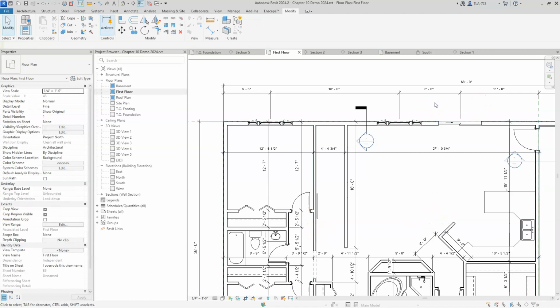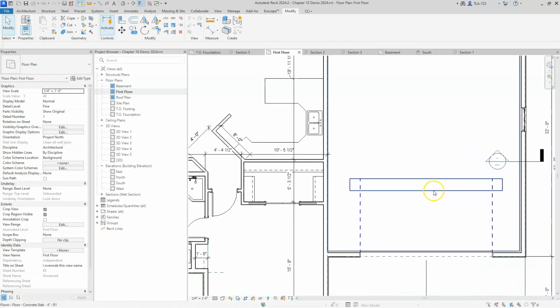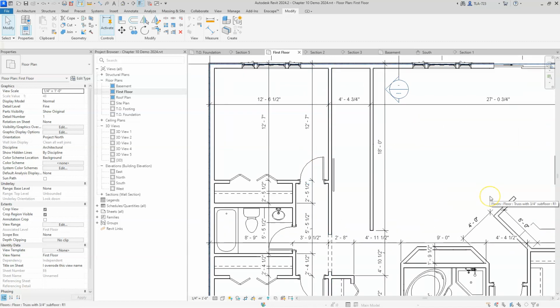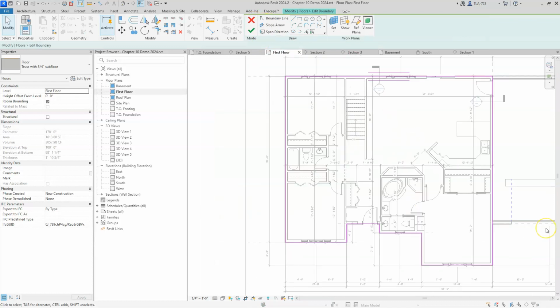So then how do we edit to create that opening? Well, you recall we created a hole in the last lesson right in the concrete floor, which we're going to get rid of later, but we need to create another one for the stair opening. So let's go ahead and do that now. And by the way, when we create stair openings, you can expect to go back and adjust that stair opening size at some point once we've done a stair section and established headroom and all those other funny things we got to do. But for now, let's go ahead and select the floor. Make sure that you have your select elements by face enabled so you can click on it. And then once it's selected, click on edit boundary, and that puts us right back in this sketch mode.